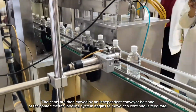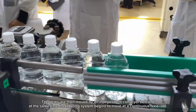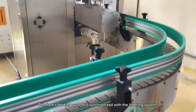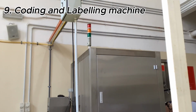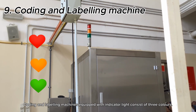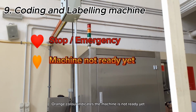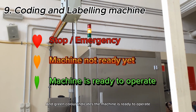The items are then moved by an independent conveyor belt and, at the same time, the labeling system begins to move at a continuous feed rate. The item's feeding system is synchronized with the labeling system. Coding and labeling machines equipped with indicator light consist of three colors. Red color indicates stop or emergency. Orange color indicates the machine is not ready yet. And green color indicates the machine is ready to operate.